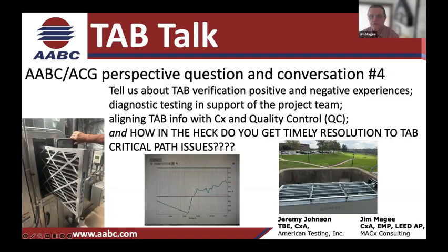The other thing I'm going to do is start with an air data multimeter and a differential pressure drop across the exterior door and see what kind of pressure your building's under. And then, on top of what you said, whether or not all the equipment's being operated and all these other parameters come into play. You can find those out early if you do a macro view instead of just starting to do readings right away, which is what I usually do.